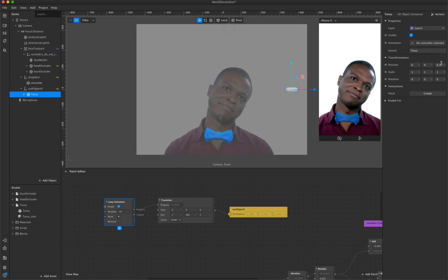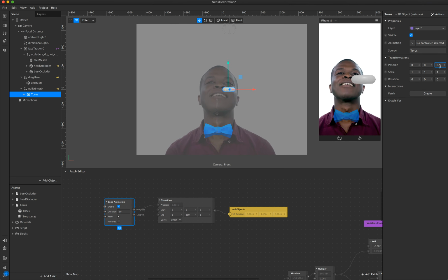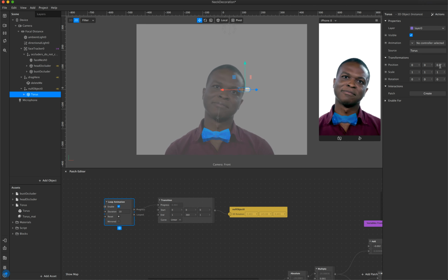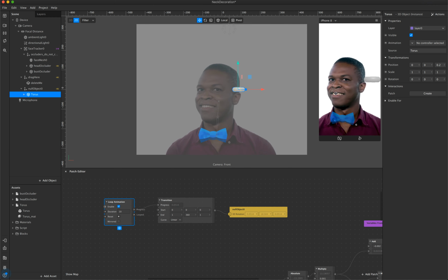It's not really interfering with Charles's head too much. It definitely seems to go around the back. Now, there's a little bit of a cut-off there, but it's not too bad. I think I'll reduce this to 2 so it's a bit closer to his head. Ah, see now there, it went in his head. That's not good. Okay, so I'll increase the distance again, back up to 3.